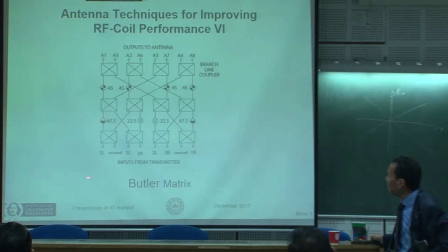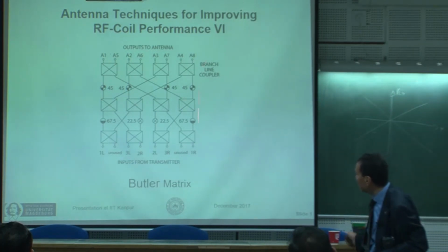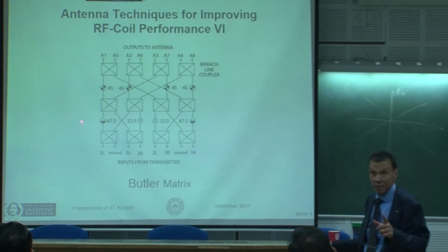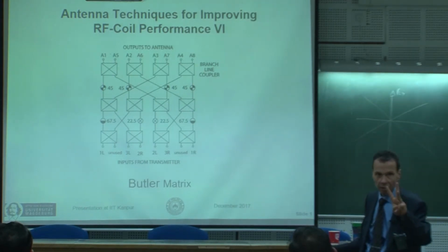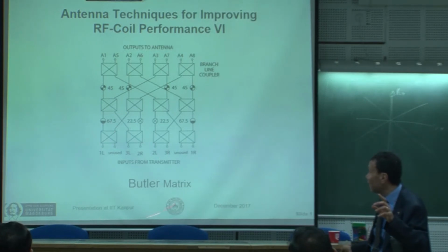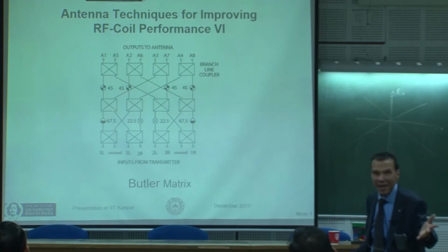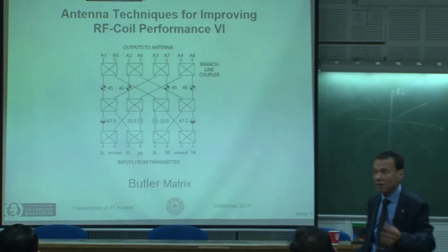If you follow this complex structure, you can show that signal 1 is directed maybe to this beam, signal 2 to this beam. This is called 8 by 8, but this number and this number are not related. So you may have 3 signals producing 3 beams, but the array itself is an 8 element array, producing only 3 beams. Or you may have 5 signals, producing 5 beams. The array elements may be 100. So in this case, the beams themselves are narrow.